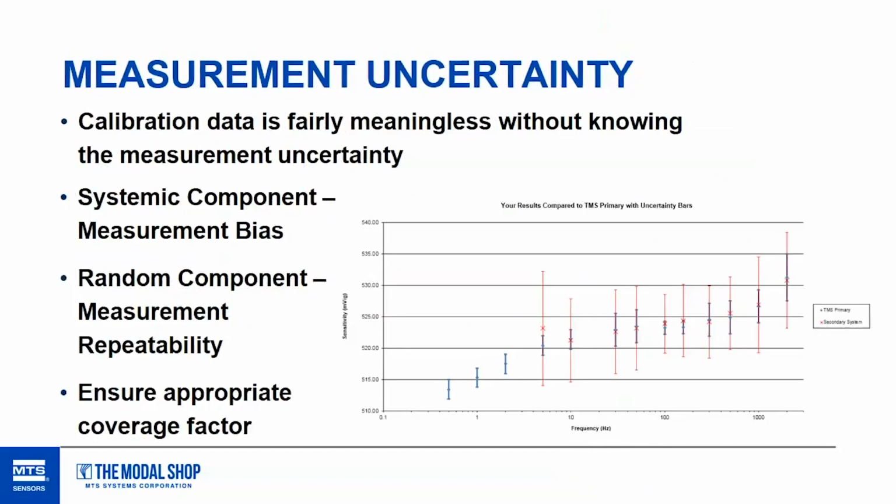And lastly, I'll kind of talk about uncertainty here. When you are doing or receiving a calibration, if you're calibrating yourself, one of the most important things to include with that calibration is not just the sensitivity of your test device, but what is the uncertainty of your reading. So if you give some value, it's pretty meaningless unless you say also how uncertain you are about that value.